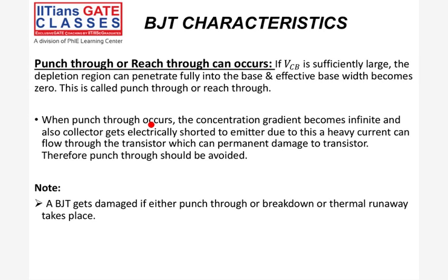The base region was already very small, and as we increase VCB, the effective base region keeps getting reduced, and the depletion region penetrates more and more into the base region. So the effective base width becomes zero at some point, at some VCB.